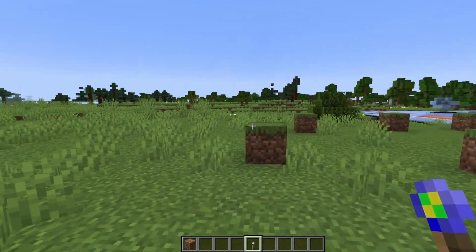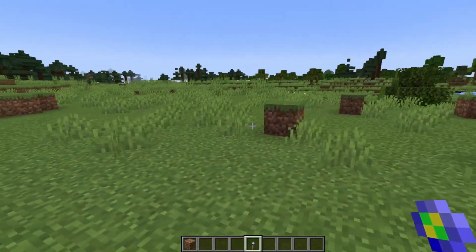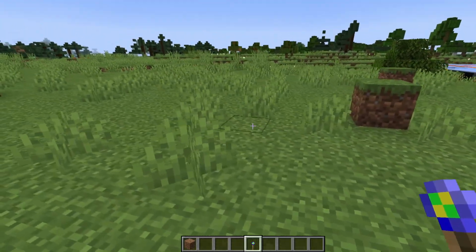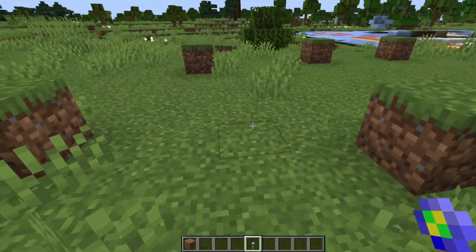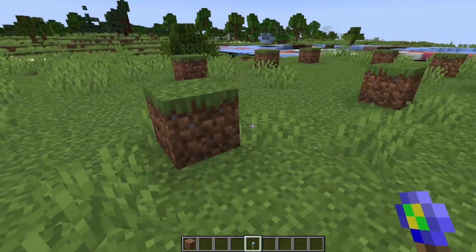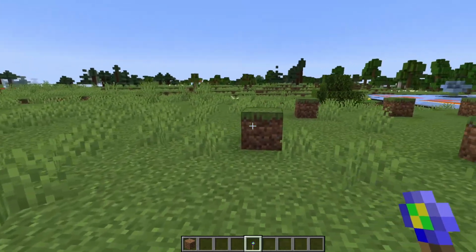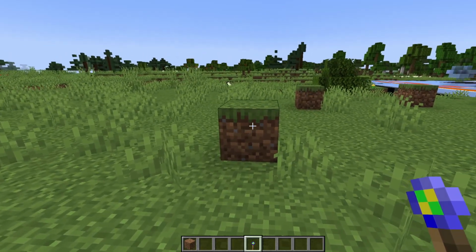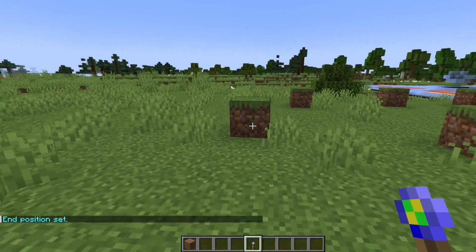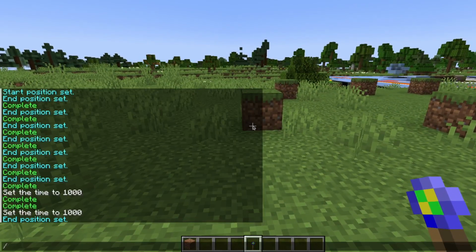So radius is going to determine the radius of our cylinder, and step is how many degrees, around 360 degrees, should it calculate a block to be placed. So you can use a large number to give you something like columns that are placed every so number of degrees around the center. So I'm going to set my new end location. That's going to be the center of my tower. And I'm going to set the height, webcom height, to 10.